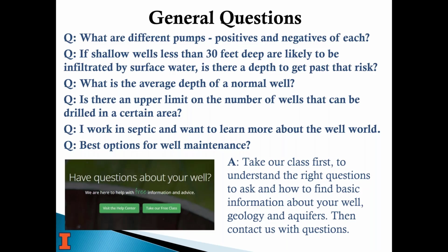So then there's a bunch of general questions that I'm not going to get to, but they're fairly basic ones, if you will. And so, there is no average depth of a normal well. It really depends on your geology and where you're at. In some areas that might be 500 feet, in other areas it might be 50 feet. It's like I used to say, well, if it's a shallower well, I've stopped doing that, because then I get asked, what is a shallow well? Well, again, it comes back to geology, what kind of aquitards there might be that protect a certain area, whatever.